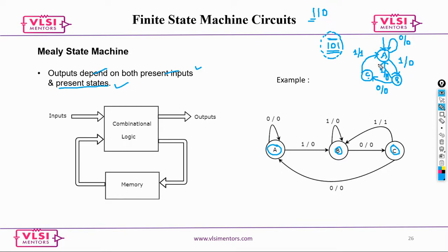Any state will have two inputs. Basically, for the state you need to define where it has to go in case of 0, and where the state should change in case of 1. So when you are designing the states of an FSM, you need to make sure both ones and zeros are always considered. Now in this case, we have done 1 bar 1. Now what if it is 0? Assume it's 1 0. Now 0 meaning what?